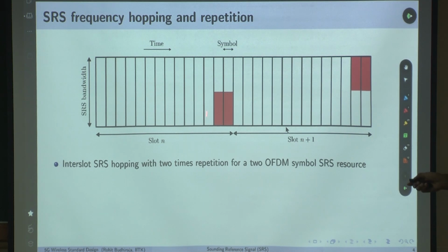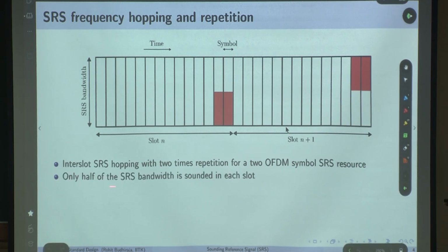3 dB comes from the bandwidth reduction, as transmit power is boosted per PRB, because the same 250 milliwatt is allocated. The repetition helps in noise averaging. We understand that whenever we repeat a signal, we get 3 dB of SNR improvement. So what are we saying here?